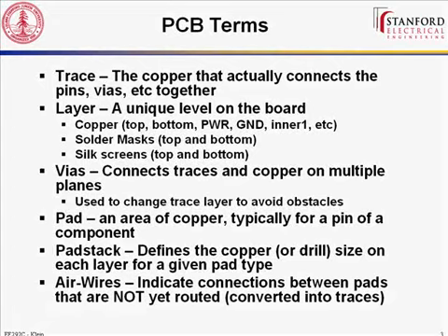Can you explain a little bit more about the relation between the solder mask and pad? Okay, so the question is, what's the relation between the solder mask and the pad itself? So the pad in the copper layer is where you're going to be soldering to, right? So you don't want there to be solder mask covering that up because that's the one part you actually want exposed for soldering. So on your solder mask layer, you'll draw an outline around the pad, and it's a negative layer. So anywhere where you draw that outline, there'll be no solder mask. And so you'll draw a layer that basically matches the pad in copper for your solder mask layer.